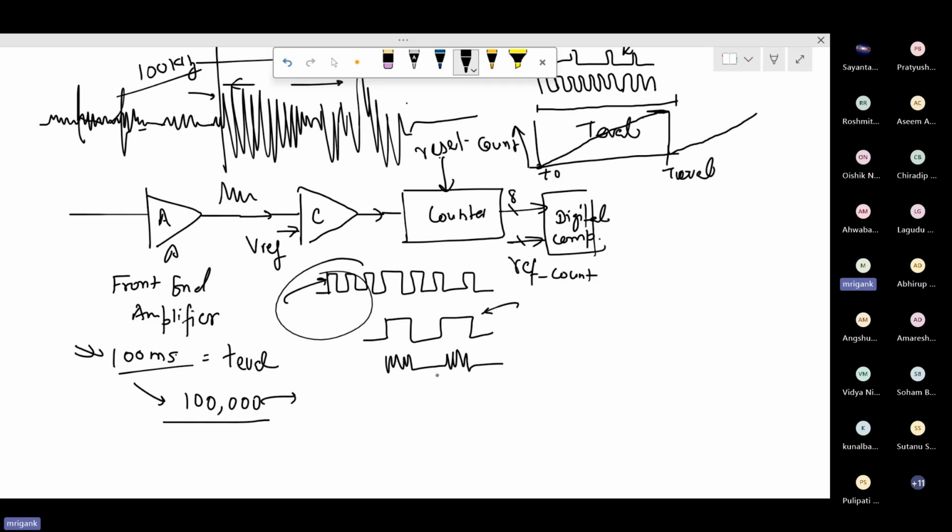Here we are talking about 100,000. 1,000 means 10 bits, and another 100 means at least another 7 bits, so a 17-bit counter may not be required. If you reject in the beginning itself, maybe we can do it with, say, just a 10-bit counter, so that as soon as it gets 1,000 such high frequency pulses within that duration, it can detect.